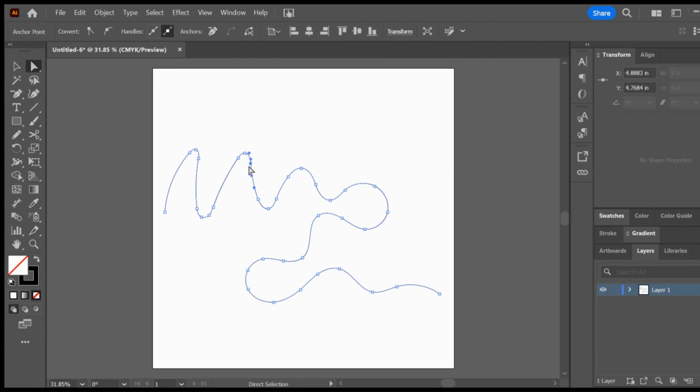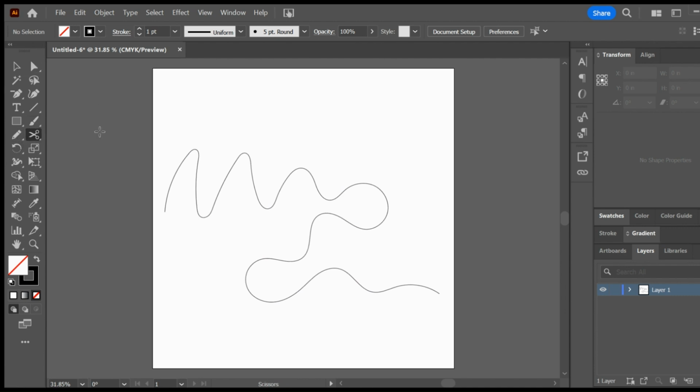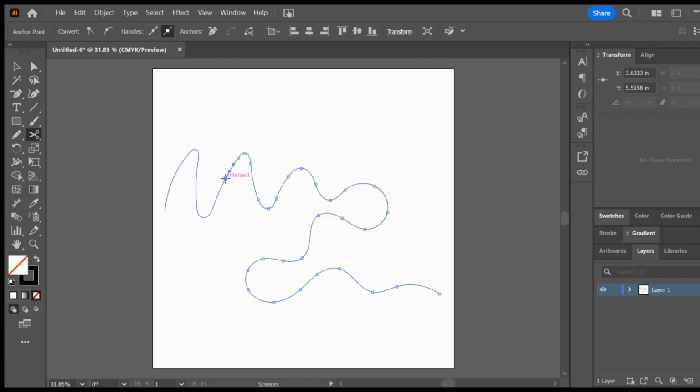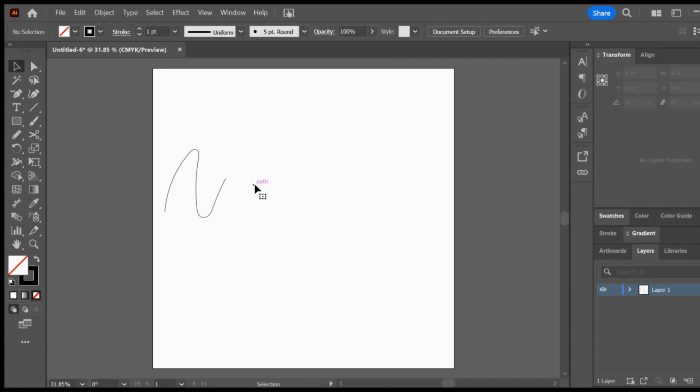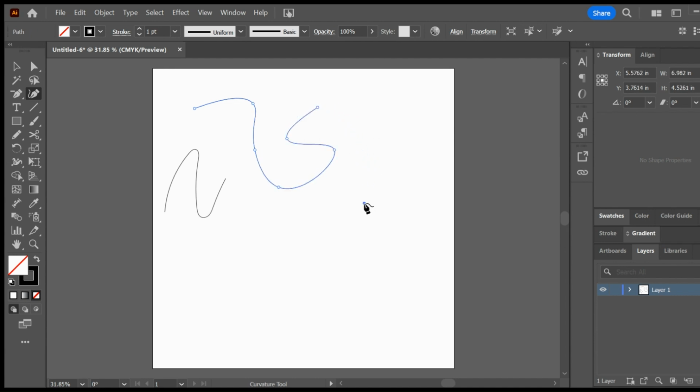Your cut tool will cut your line. So rather than rubbing out your line, you basically have to cut it and then just delete a section. And then a lot of people use the curvature tool. I don't, so I'm in no position to teach it, as I only spent 10 seconds learning how to use it this morning. But what it does is effectively keep drawing a line. If you double click that line, it'll stay straight rather than in a curve. And the only way I can figure out how to stop this is by pressing the selection tool.